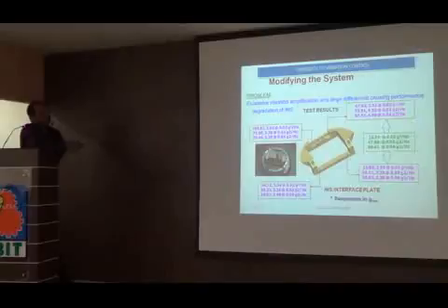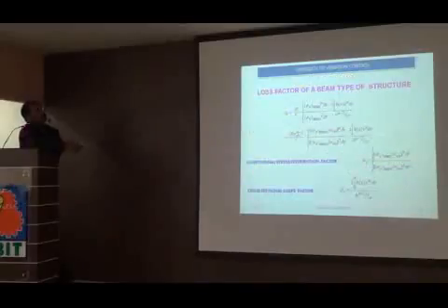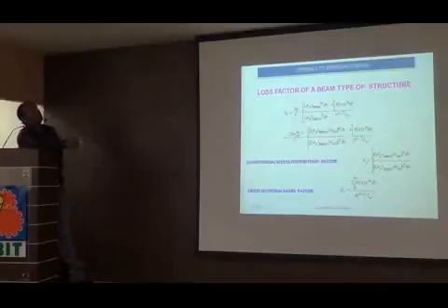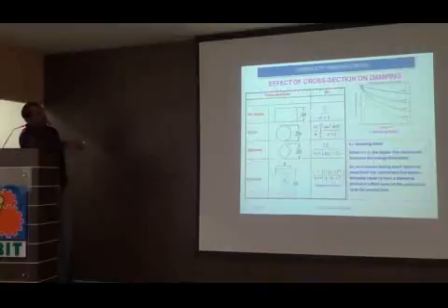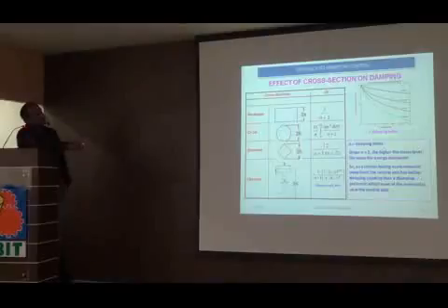So we had come to the conclusion that what we call loss factors, as damping in the system, can be improved if you know the theory behind it. When we saw, yes, it can be improved from the beam type structure based on this formula. Then we found that the cross section shape can be changed. How did we change it? When we studied, we had this literature available. If it is an I section, yes, the I section has better damping compared to other sections.